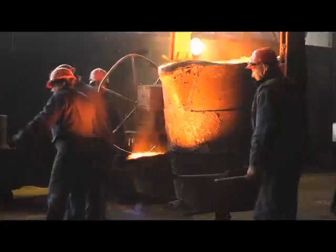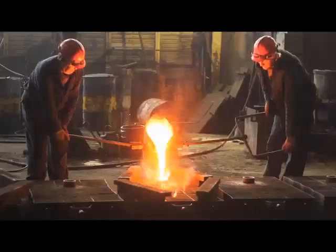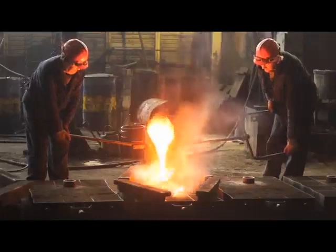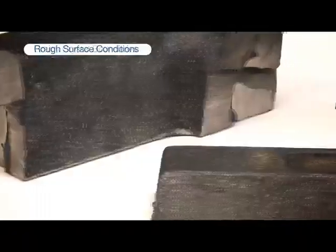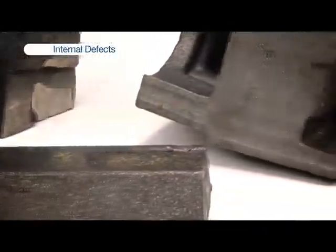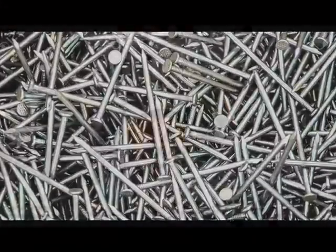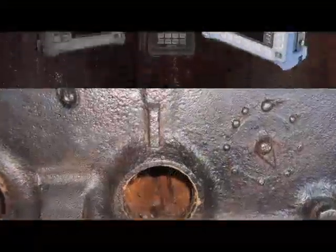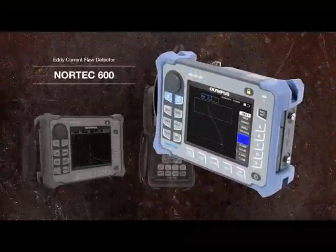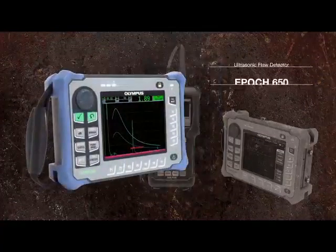Cast components are manufactured by pouring molten hot metal into a sand mold. The molten metal is then cooled and solidified, forming the part. As a result of the manufacturing processes, castings generally end up with rough surface conditions, grainy crystal boundaries, and have the potential for internal defects. Due to these characteristics, there are a number of non-destructive testing techniques that apply to cast components. These include eddy current tests for surface cracks, and ultrasonic tests for thickness, porosity and voids, and graphite nodularity.